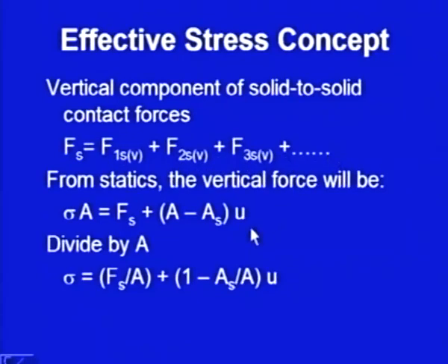Now, from statics, you know that the total vertical force, which is the total stress into area, will be equal to the force borne by solids plus the force borne by the pore water.